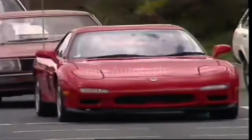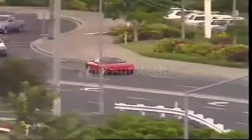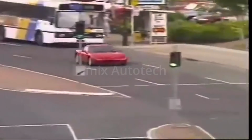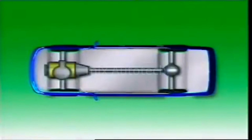A vehicle starting from rest needs a lot of torque, but once it's moving, it can maintain speed with only a relatively small amount of torque. A higher gear ratio can then be selected and engine speed reduced. A conventional vehicle with the engine at the front and driving wheels at the rear uses a drive shaft called a propeller shaft to transmit torque from the transmission to the final drive.